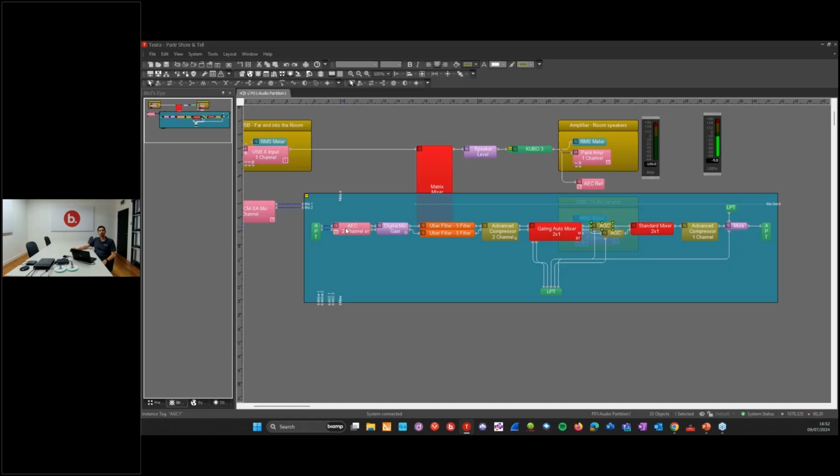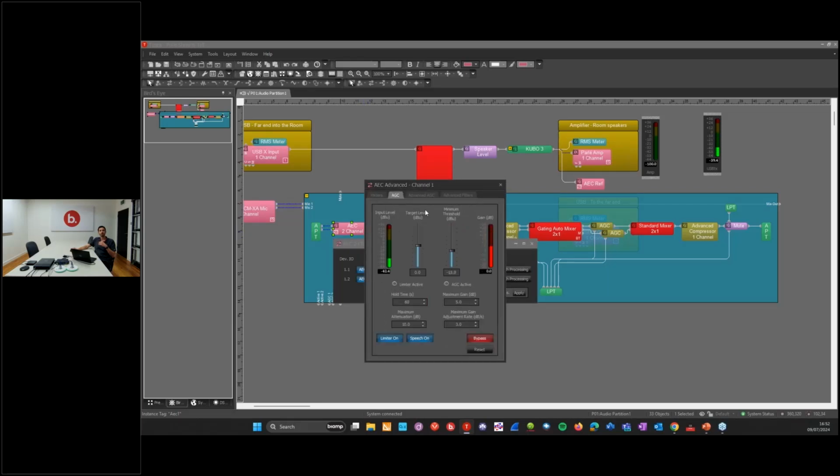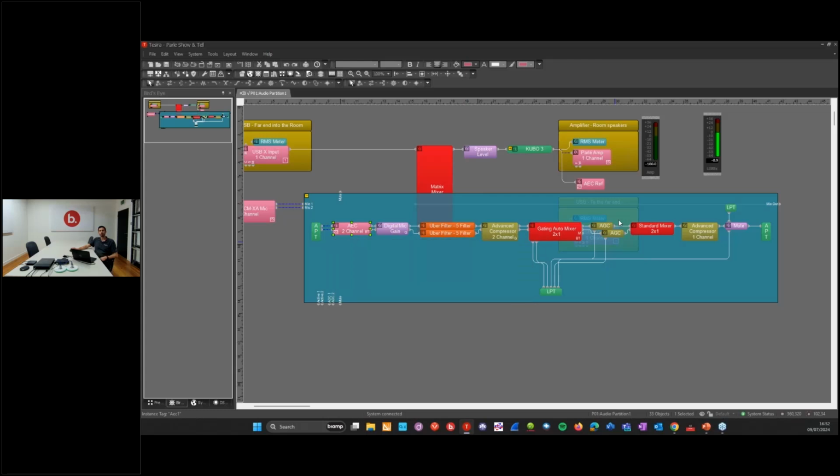Following that, and I mentioned the AGC is disabled in the Beamtracking AEC block, and there's good reason for that. There's actually automatic gain happening in the microphone itself. Obviously, it's making decisions on an active talker using essentially a real-time algorithm saying, yes, that is someone I want to listen to. And as it performs beams, it will add gain as necessary. Now, if you have one process, i.e. the microphone adding gain, and then immediately afterwards you have another process that's doing automatic gain control, the two are going to counteract each other. It's going to say, that level's increasing, I'm going to decrease it. And that's why we disable it in the AEC block.